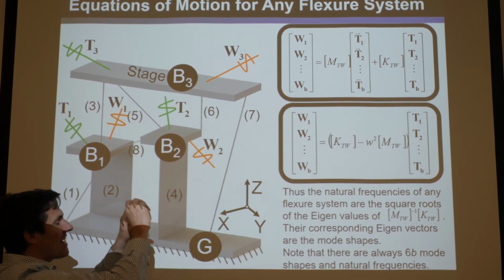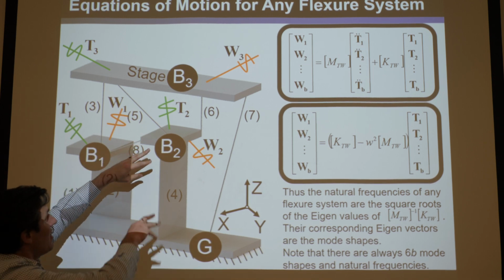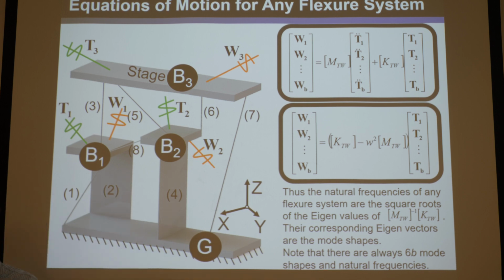You keep breaking it down and adding more stages, and connecting them with these flexures. You'd break it into more finite elements, until you finally break it down into atoms and their atomic bonds, where the nucleus is the mass and the bond is the stiffness, and now you just keep adding more natural frequencies and mode shapes according to the analytical theory.